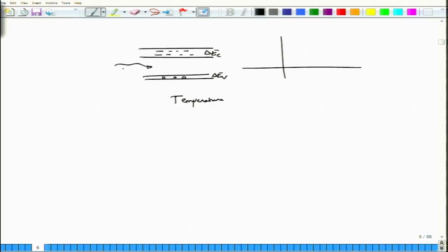Once the energy comes in, if you have already created a number of electrons in the conduction band and holes in the valence band, the electrons which are there have pushed down. So these are the electrons which are not participating in the conduction, whereas the holes are there. But now with h nu, Auger recombination can occur, that is, the electrons can absorb this energy and move into a higher energy state, and the valence electrons can do the same thing and push this boundary of the valence holes below it.